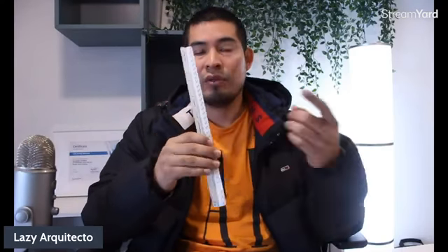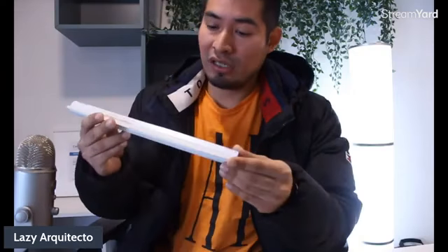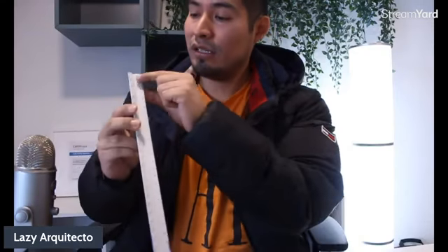And what I was saying from the viewport is you need to pick a scale that is most used, so that whoever receives your drawing and prints it to the correct size of your sheet, which in this case is 24 by 36 inches, can use it. Let's say if I pick a scale of 1/4 in AutoCAD, this person, when he prints the drawing, can use a scale like this and find the 1/4.